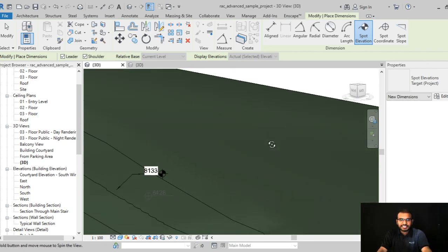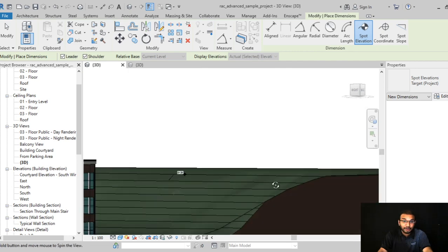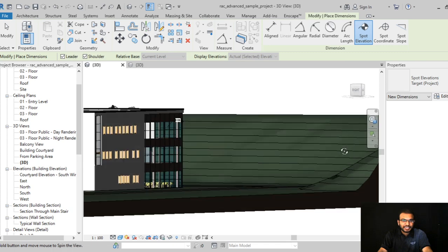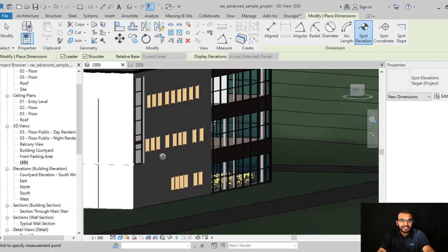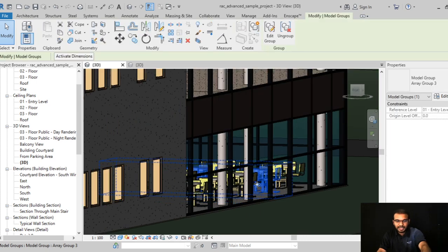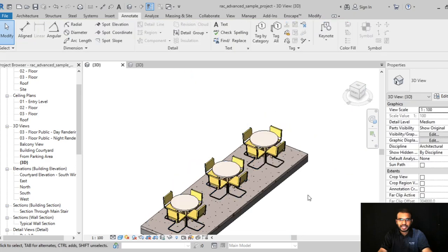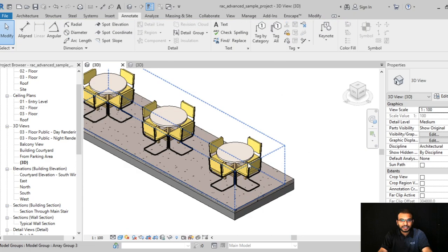And as I mentioned before, you are playing in a 3D environment, which means you are completely live here. Let me do one thing. If I select this particular area, I want to see only the furniture detail. I select the furniture and click a small option, and you get only that particular entity.